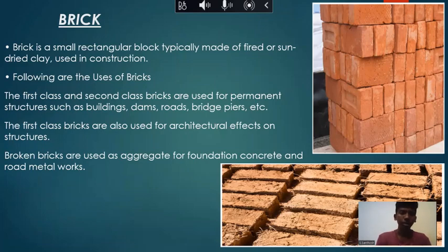Over here you're seeing that it's said first class bricks. So over here we mean that the bricks are classified into different types or different classes based on how well they are burnt or depending on their shape and size. So when you're saying about the first class bricks, they are all of the uniform shape and uniformly burnt. But then when you go down further with second class and third class bricks, you might not have some uniform burning done in the brick, or they might not be having a regular shape in them.